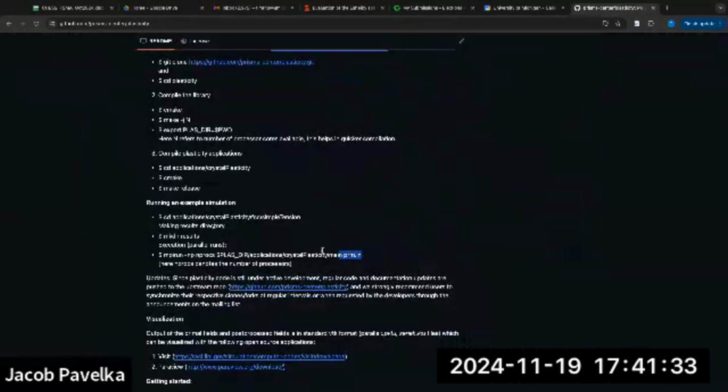So Vitaly, if they want to run it on the PRISMS code, you just use this part, right? Without the MPI? No, you can use the MPI. Do they have the MPI on the PRISMS toolbox? You do like mpirun -np 4 or 6. Okay, yeah, so you won't get 32, but yeah, you can use this whole command with np maybe. It depends how many CPUs you made active to your virtual box when you installed it, but 4 or 6 or 8 or something like that. And then yeah, you'll also be running it in parallel.